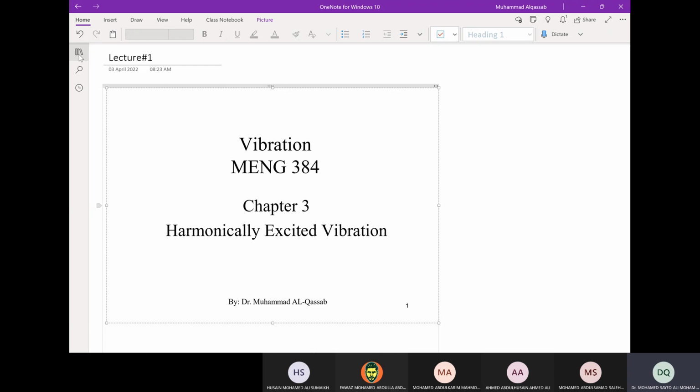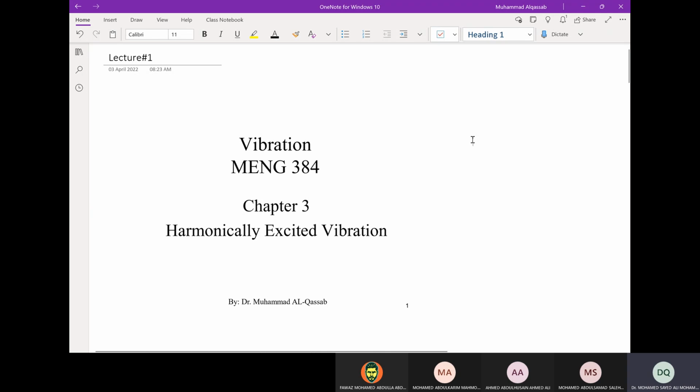Regarding the amplitude, we find the peak, the maximum, and we call it the amplitude. For underdamped, the amplitude is at the beginning of each cycle, so it varies. For undamped, the amplitude is the same. And if I just focus on the frequency in the free vibration, it was a function of the system parameters. For the spring mass system, it is a function of K and M. And we assume it is constant for a linear system and independent of initial conditions.